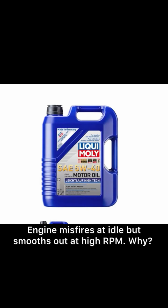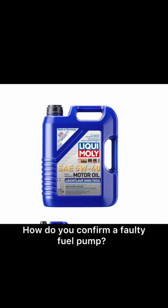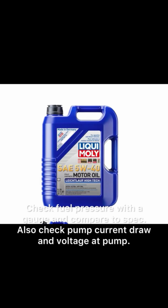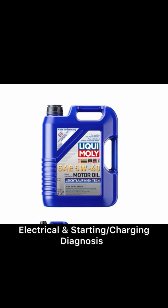Engine misfires at idle but smooths out at high RPM. Why? Likely vacuum leak or dirty injector affecting idle mixture more than high RPM. How do you confirm a faulty fuel pump? Check fuel pressure with a gauge and compare to spec. Also check pump current draw and voltage at pump. What does a P0302 code mean? Cylinder 2 misfire detected.